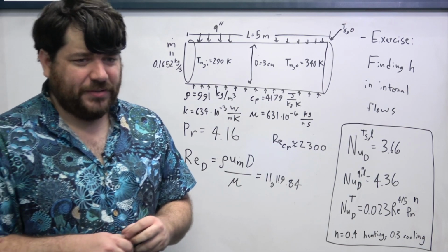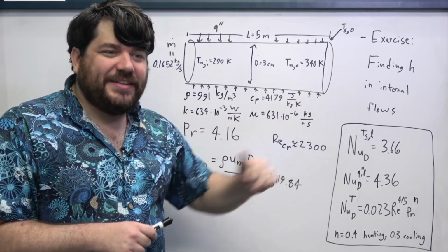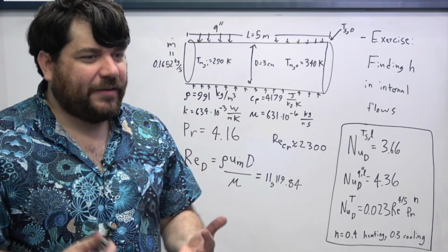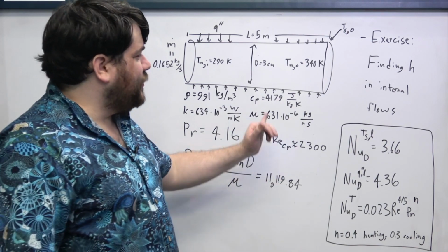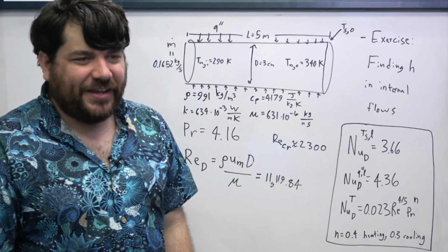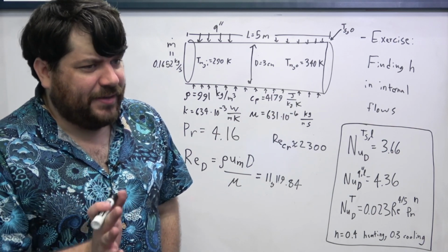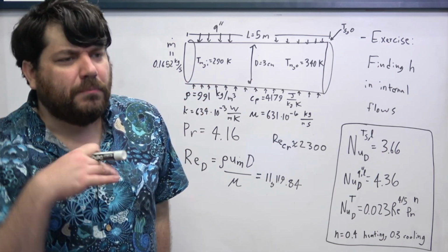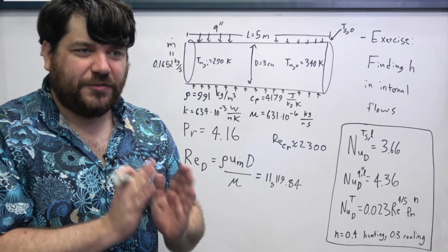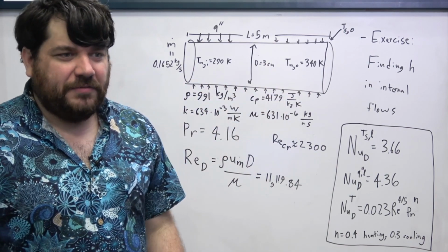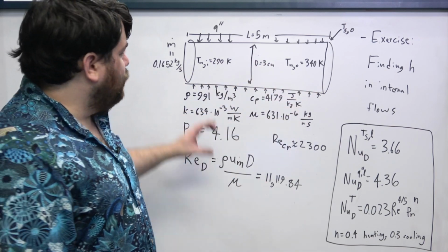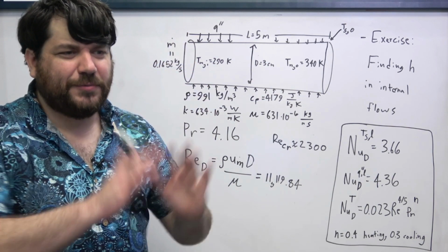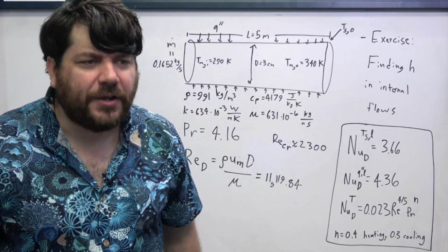And one thing that you should know about the Nusselt numbers is that, remember, we had concluded that the h's don't change. And so because the h's don't change, we also don't have to worry about locality, right? An h that I calculate here is going to be the same as the h that I calculate here. That being said, that's only true if we neglect the change of the flow that happens in the entrance region. But for most piping systems, that entrance region is so small relative to the length of the actual conduit that we can neglect the correction that would happen by miscalculating the heat transfer in the entrance region, and just pretend like the flow is fully developed everywhere, and then off we go.